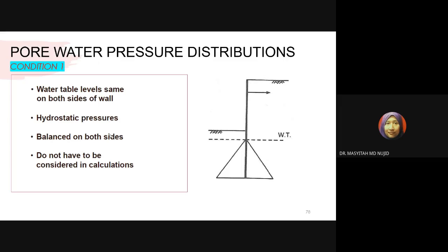Okay, remember when we use the prop anchor or we use the cantilever wall, the purpose is to retain soil from movement. So the soil can be considered by taking the weight, we can have the weight of soil, for example, for dry soil or for part soil, and also sometimes soil also has additional weight which comes from the water pressure, or we call it here a water table.